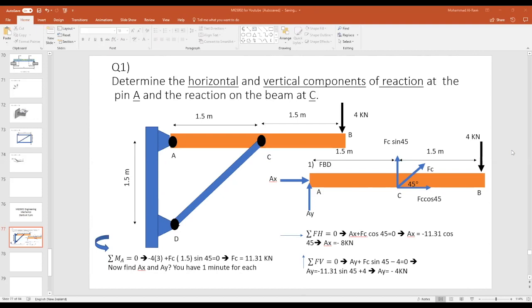Yes. Many of you are sending me the right answer, which is really good, and really awesome to see that level. So technically, when you solve this kind of question, don't be afraid that you assumed the direction of your support reaction wrongly. Don't be afraid of that because we have a solid piece of information here, which is the 4 kilonewtons. The only one I put in black to show you that this force is going downwards, and the rest is all assumptions based on the structure and how the geometry works.